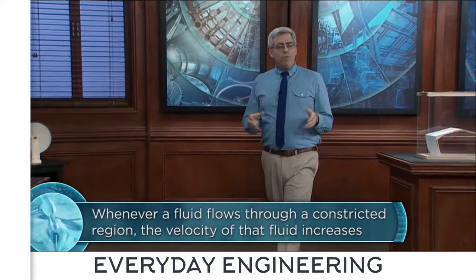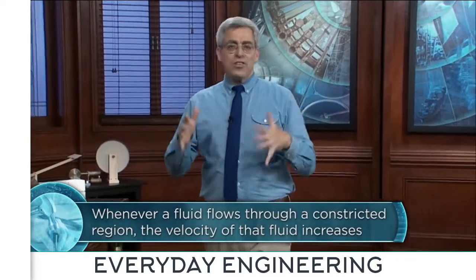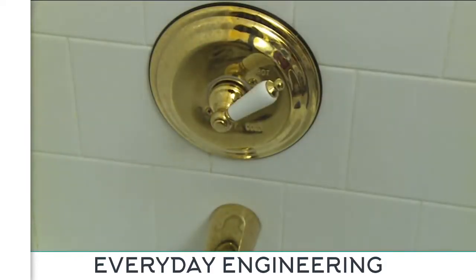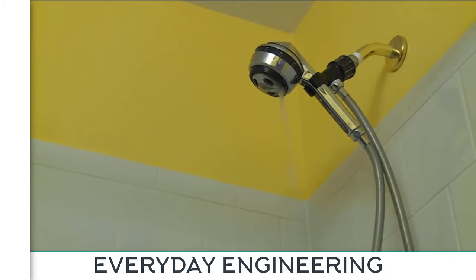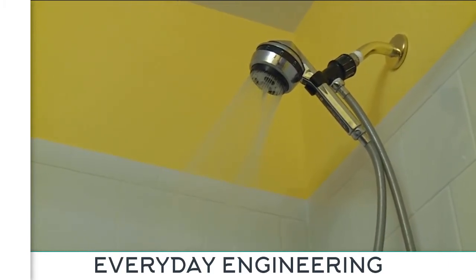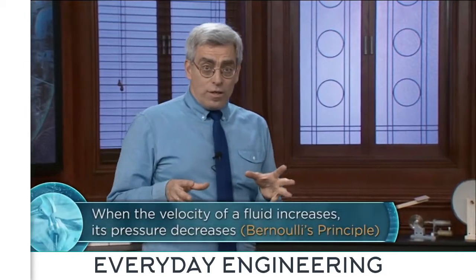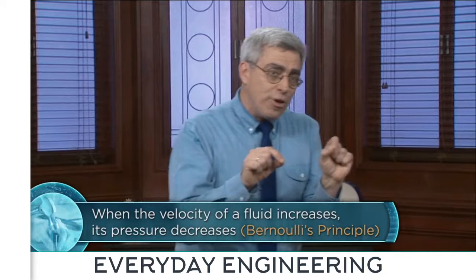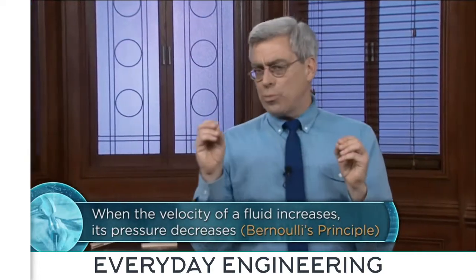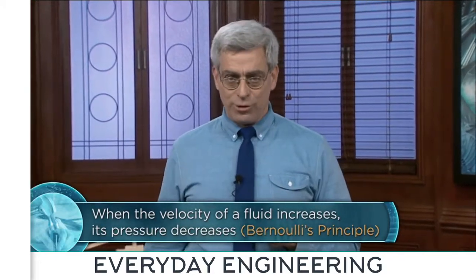First, whenever a fluid flows through a constricted region, the velocity of that fluid increases. You actually observe this phenomenon every time you take a shower, as slow-moving water in a pipe is transformed into a series of fast-moving jets emerging from the tiny holes in your shower head. Second, when the velocity of a fluid increases, its pressure decreases. This is called Bernoulli's principle, named for Daniel Bernoulli, who discovered it back in the 18th century.